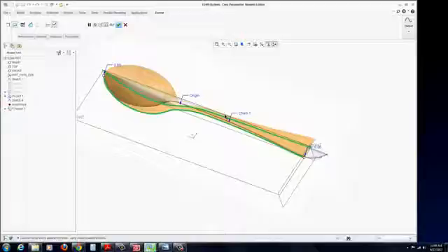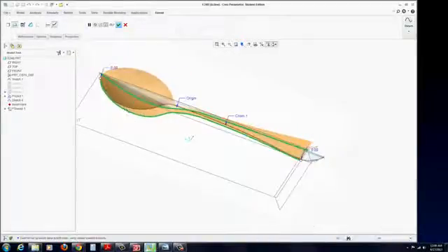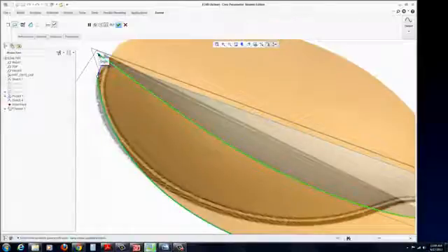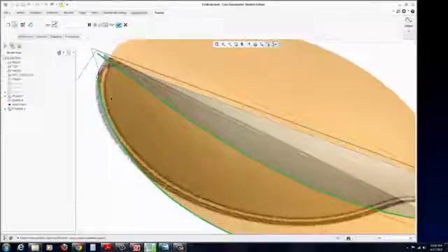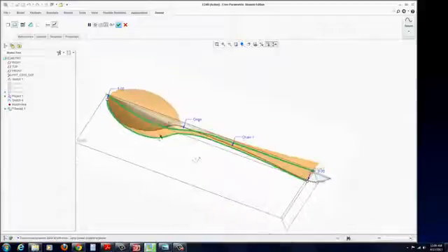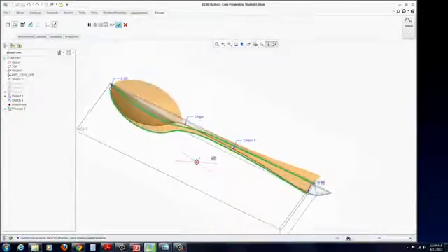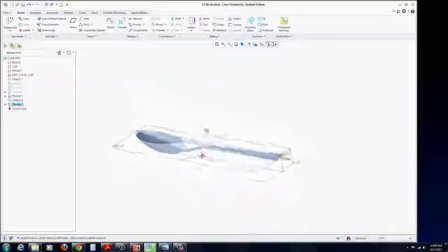If you're not seeing it, it's a possibility maybe you have a ripple in it. It's just too complex. Or if you didn't extend this center further beyond this edge, or if they're connected and actually intersecting, I've seen issues with that. So just be careful with that. I'll just make sure it's disconnected a little bit of distance away. And now we can go ahead and hit the green check mark to apply, and we've got our surface for our spoon.